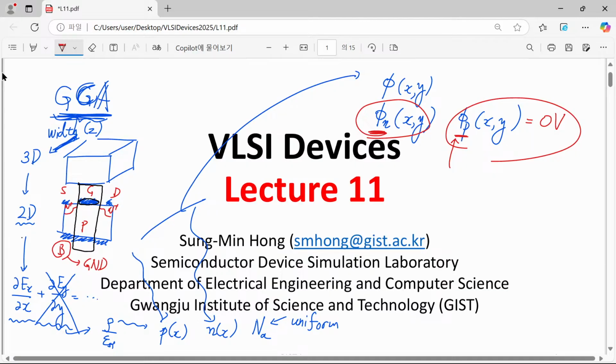Well, we have to actually calculate this electron quasi-Fermi potential as a function of general 2D position, but a great simplification was possible because now we say that although we have to calculate this 2D-wise, it can be reduced to just a 1D-like, or channel directional, calculation.